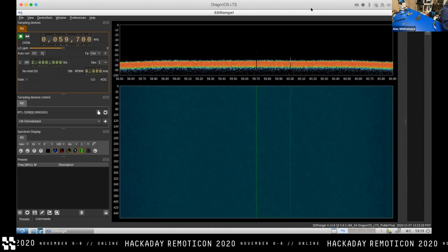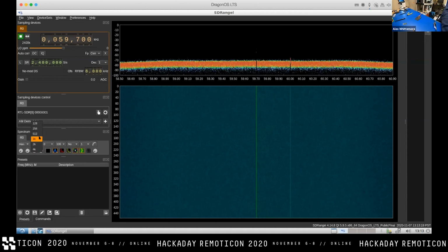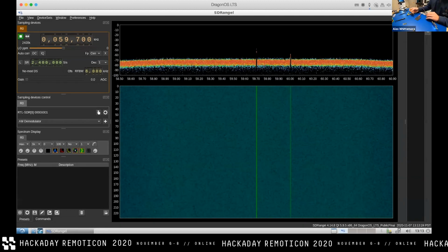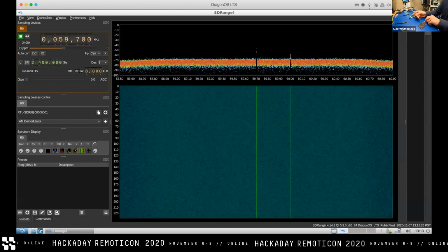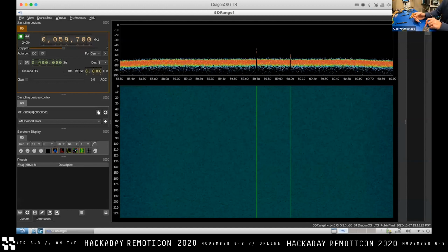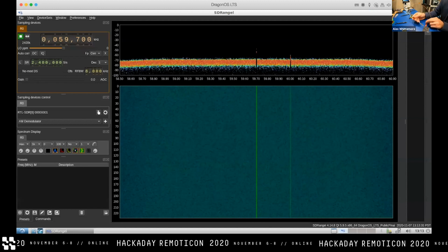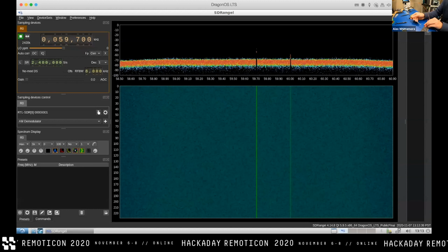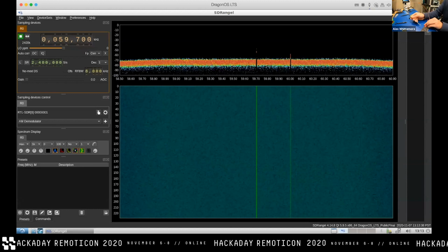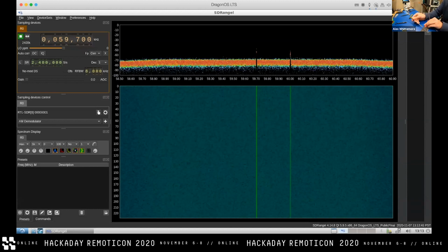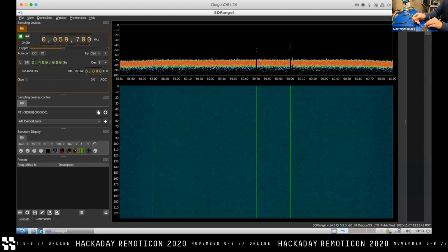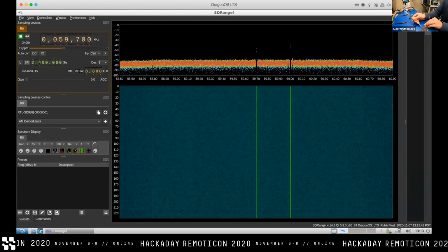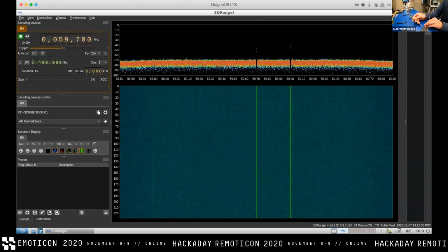Actually, just for giggles, I'm going to make the FFT a little shorter. This will make the peaks a little bit wider and more obvious. So now we're going to recreate the test that we had earlier of, okay, where is that pin in question? I'm going to rotate the probe so that the hoop is perfectly projected down onto the wire of the pin. And we're going to wave that around and try to figure out, I guess it's a little bit tough here to see what the actual peak is, and our other tool will show this a little bit better.